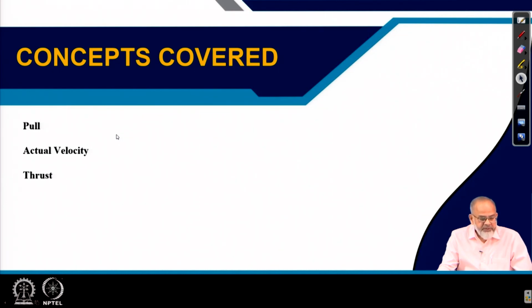The setup which will be used is a single wheel tester, and there we will try to vary the pull, the load, and the inflation pressure. In fact, tractive efficiency is a function of load, of pull, of soil condition, and of inflation pressure.